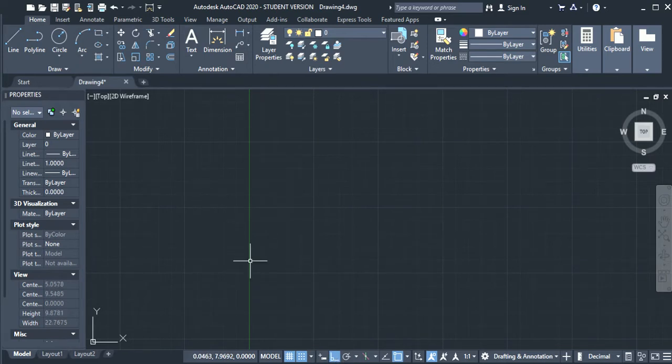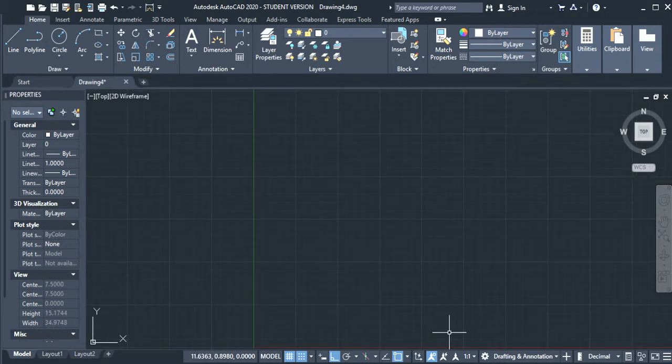I'm going to hit Escape. E is erase. I'm going to zoom back, so Z and A gets me back to my template size. This here locks me onto different things. L for line, hit enter. It draws a line. If I do escape, that takes me out of the command, but if I hit L again for another line, this tool allows me to snap onto these points. You see the little green point, the triangle is a midpoint, and that box is there. If we turn that off, you'll notice those disappear. So that's really helpful for this assignment. Go ahead and leave that on.